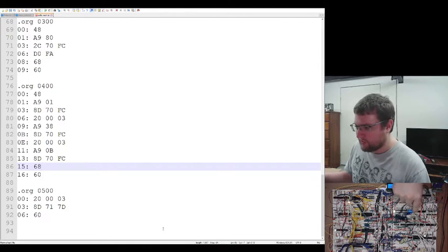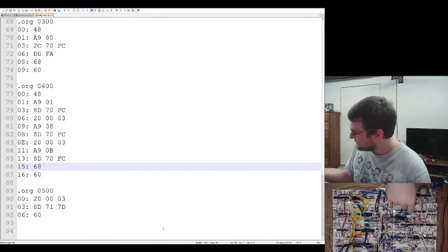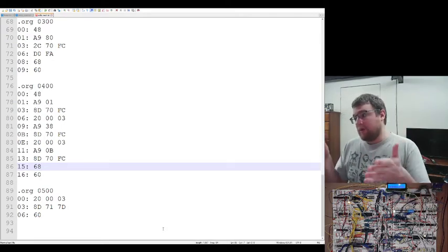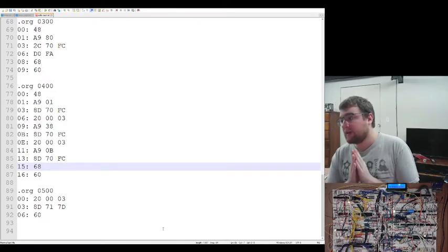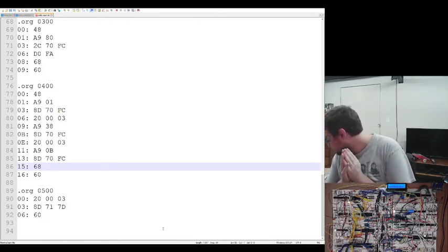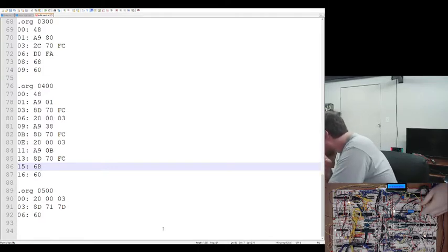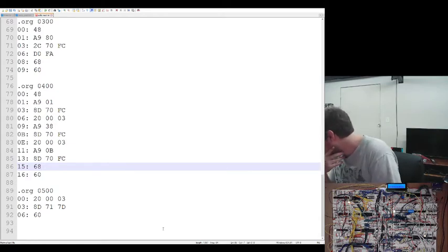Because if you have an active low OR, it becomes an AND. So we'll make an active low OR gate for this up here, and it'll be good. We just have to figure out where to grab that from. But that should be easy because it was the old spot. So as long as I haven't, in fact, yeah, I still have the wire from the old spot here. So it should be possible.